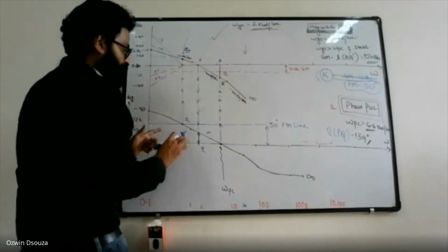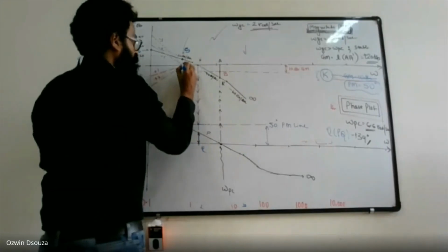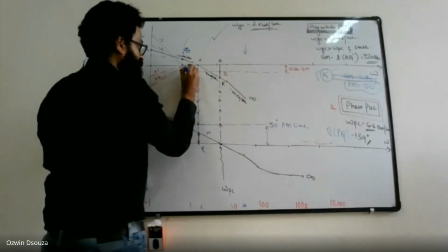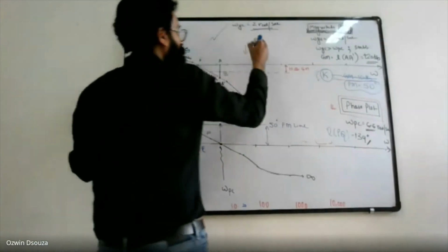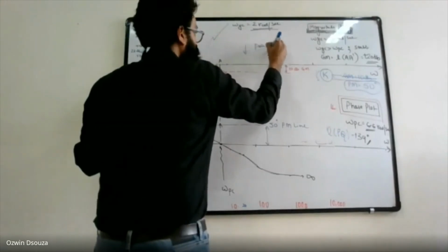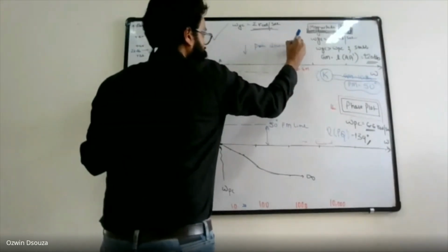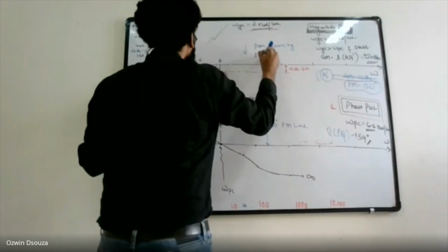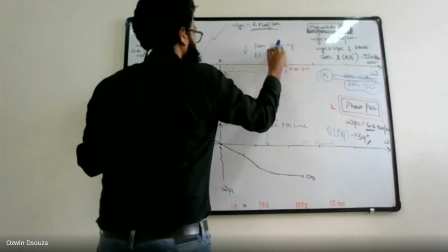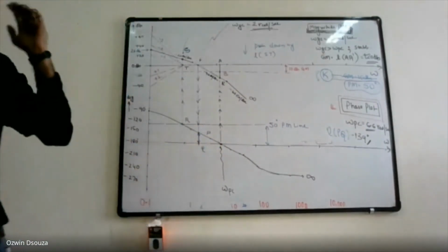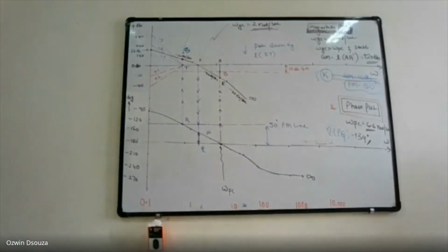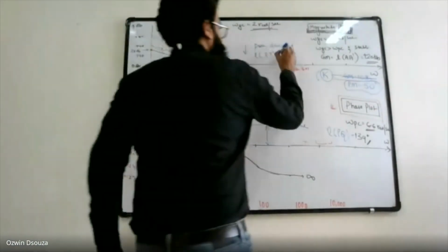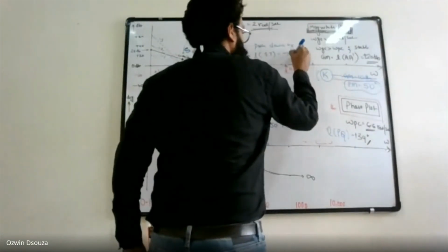So what you can do, PQRS. So this point on 0 dB line, you can take it as T. So push down by length ST. Okay. So you will have to measure that length ST. So length ST, you will get it somewhere close to minus 14 dB.